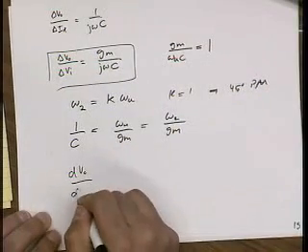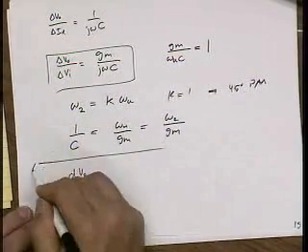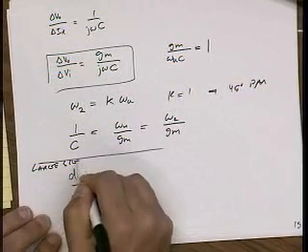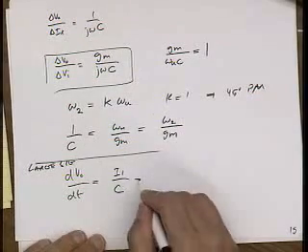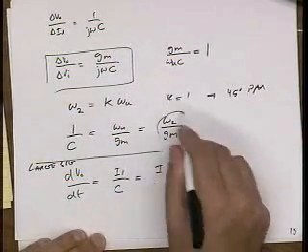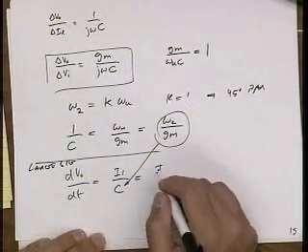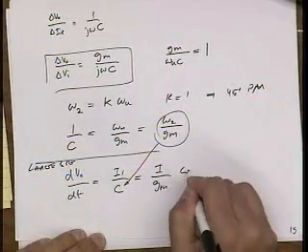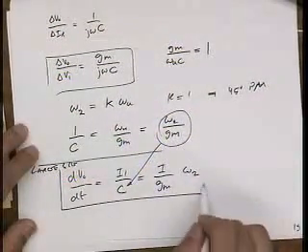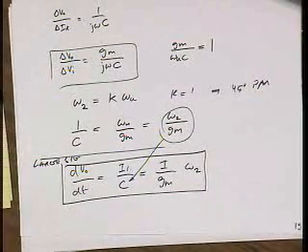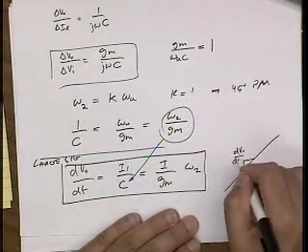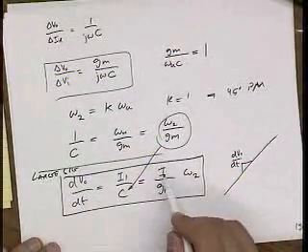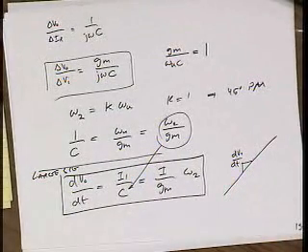So when I write the output for large signal, now back to large signal, I can just substitute for 1 over C this expression, and I get a really interesting equation, which tells me that the slew rate, which I want to be as large as possible, this is that ramp rate, is related to I over Gm.